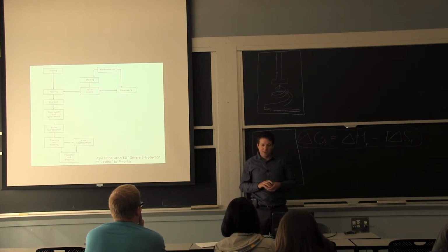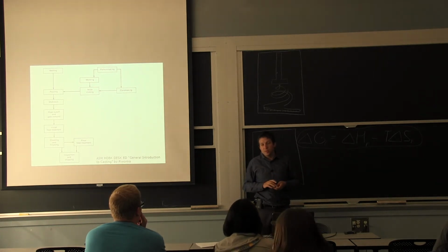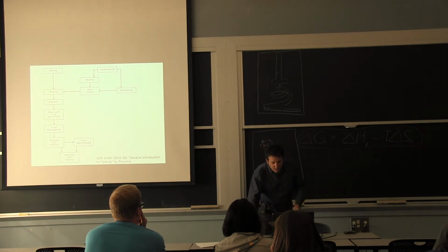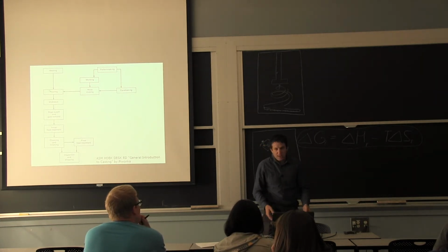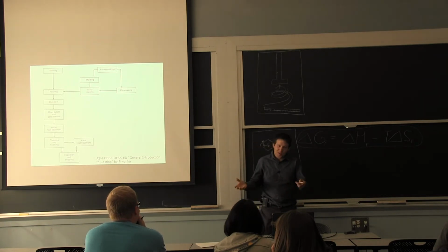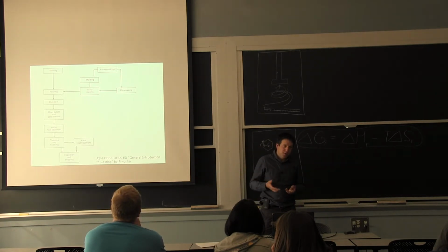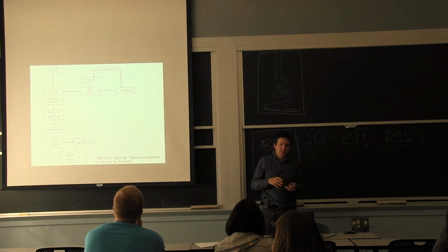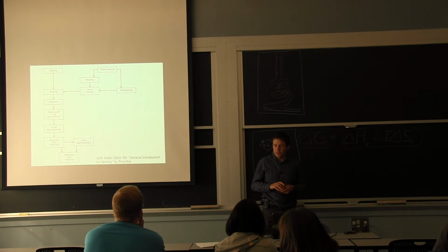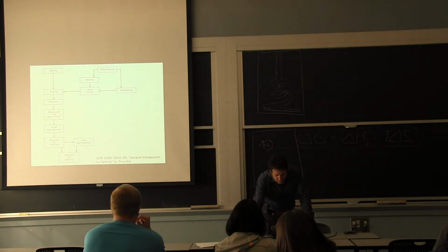with consumable molds, and you come into entrapped air or entrapped moisture, and a lot of things you're trying to eliminate, and still have enough ductility so it doesn't break. A good surface finish, because we've just talked about how it's affecting the quality of the part, the quality of the contact between the mold and the metal. So that was one area. There isn't that much going on just for melting it. But in terms of protecting it from the environment, do I need to use vacuum or shielding gas? Is it okay to use air? That's where the expertise comes in, to put it this way.